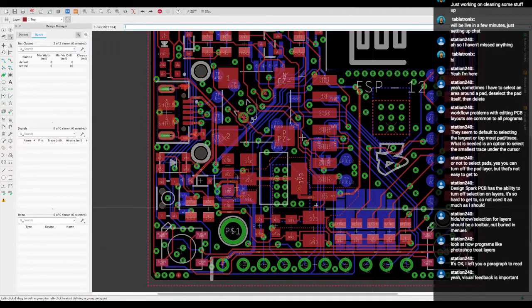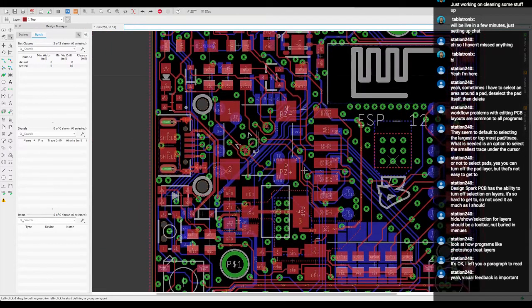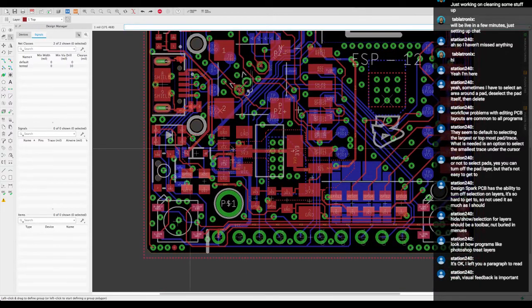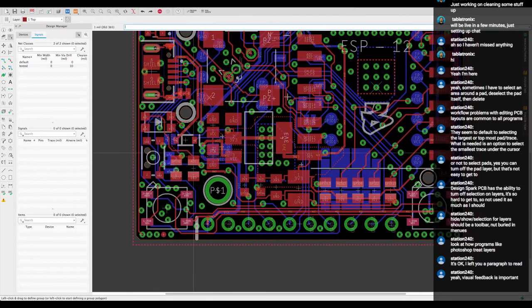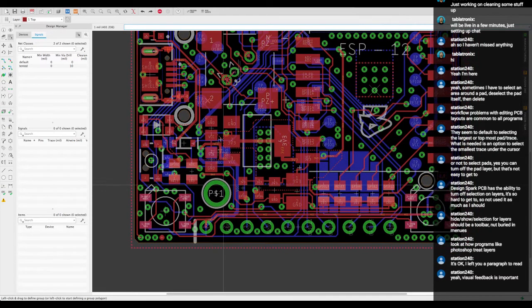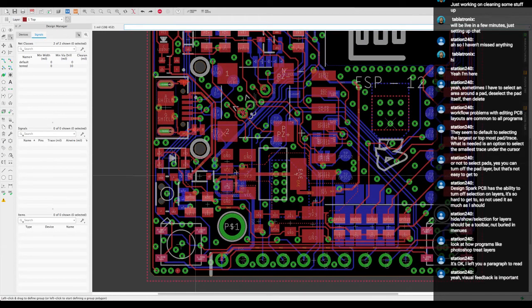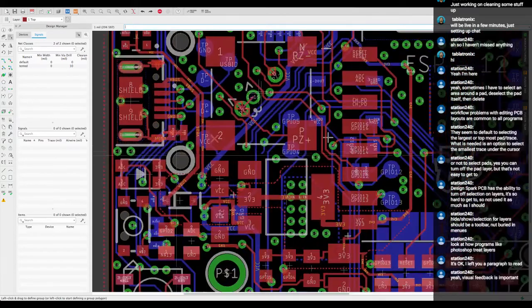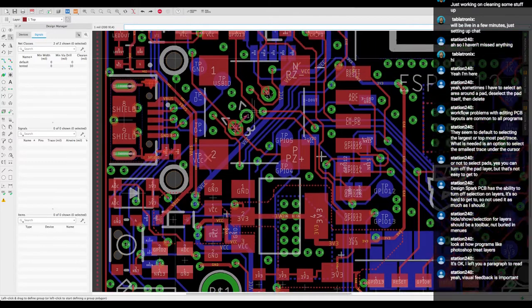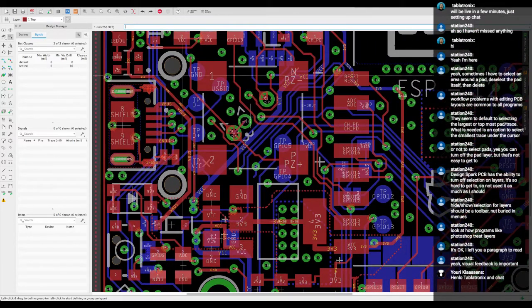That, and I had to squeeze in that resistor over there, squeeze in a resistor over here. Move this around. I had to add a resistor for this opto photodiode. Oh, this one. I added these physical mounting. These are the mounting holes. These are more like alignment slots. Like, they're not electrically safe. I wouldn't really put a screw down on here because it probably won't short anything.